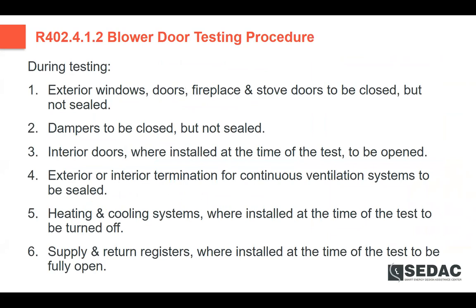So your fireplace dampers you're going to close them, but you're not going to tape them and seal them shut during normal occupancy. So we want to make sure interior doors are open, so that air can flow where it needs to during the testing. But really we want to make sure that the building is in a livable state.